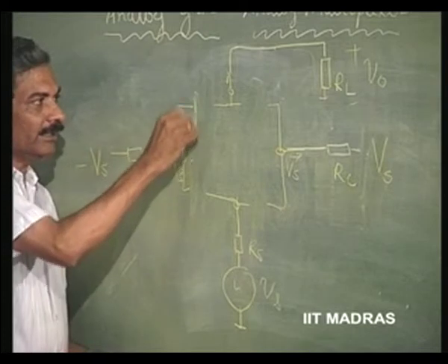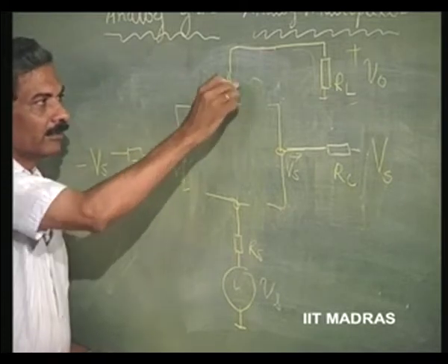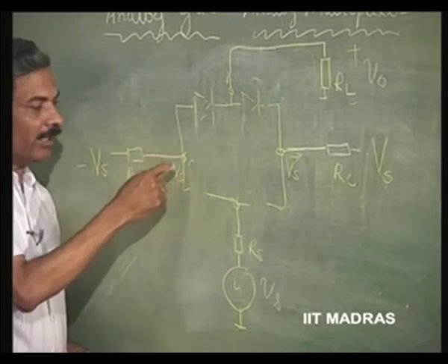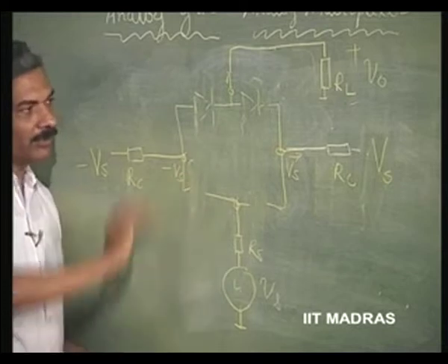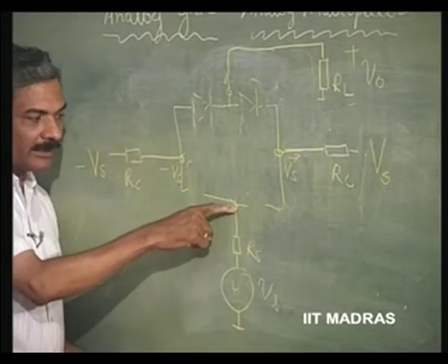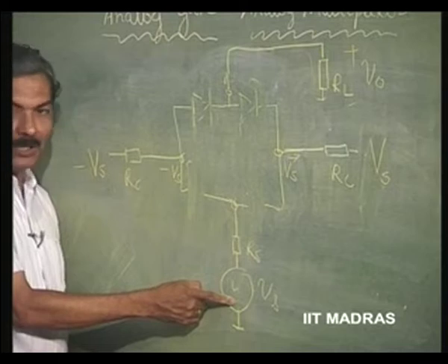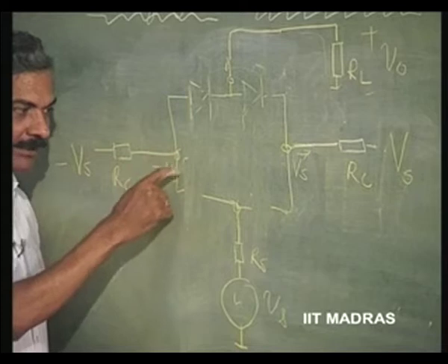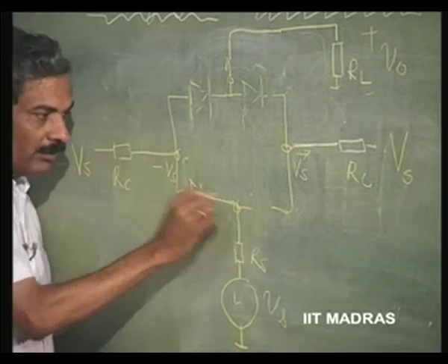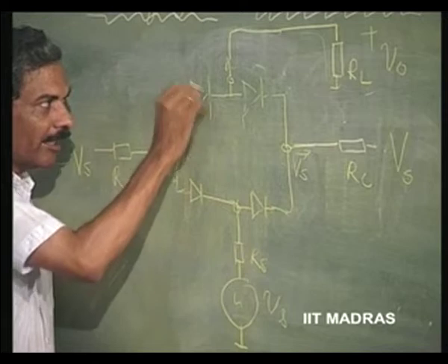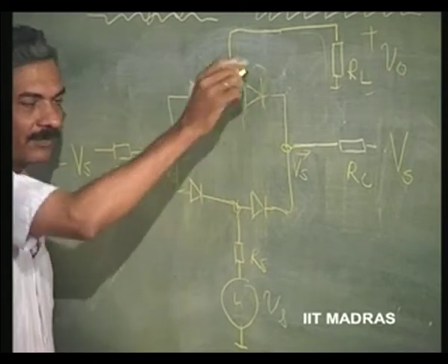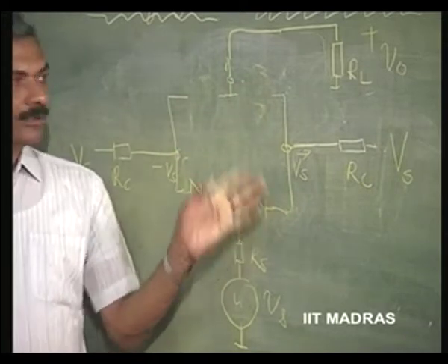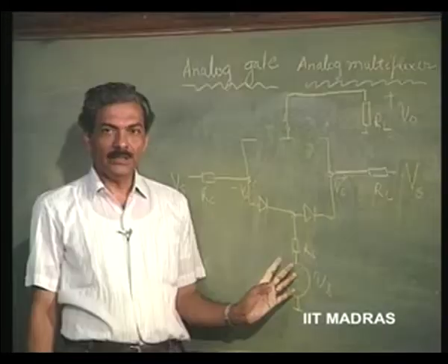Imagine that these diodes are existing here. So, these are reverse biased to the extent of Vs, both of them. So, they will remain disconnected. Only thing is the reverse bias here keeps changing depending upon Vs. In order to maintain these diodes under reverse bias at all times, these diodes are of no concern; if they are kept open, there is no problem. Even now the load is disconnected from the source.